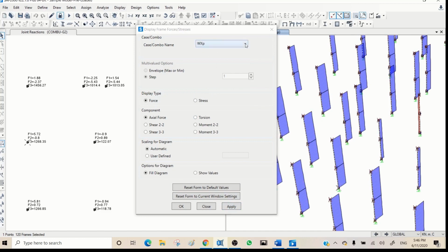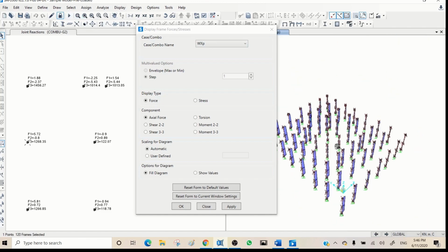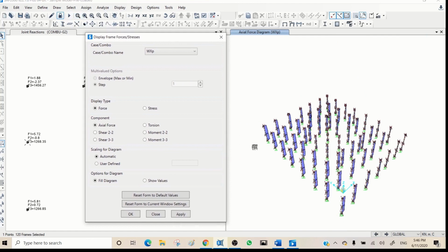So this is wind XP. That means pile in one side is under compression and the other side under tension. So if I use this on wind XP, you can see these numbers are changing. Some parts are less under tension, some parts more. Why this governs? Because we have uplift roof wind load, so that uplift governs the lateral upward and downward load.